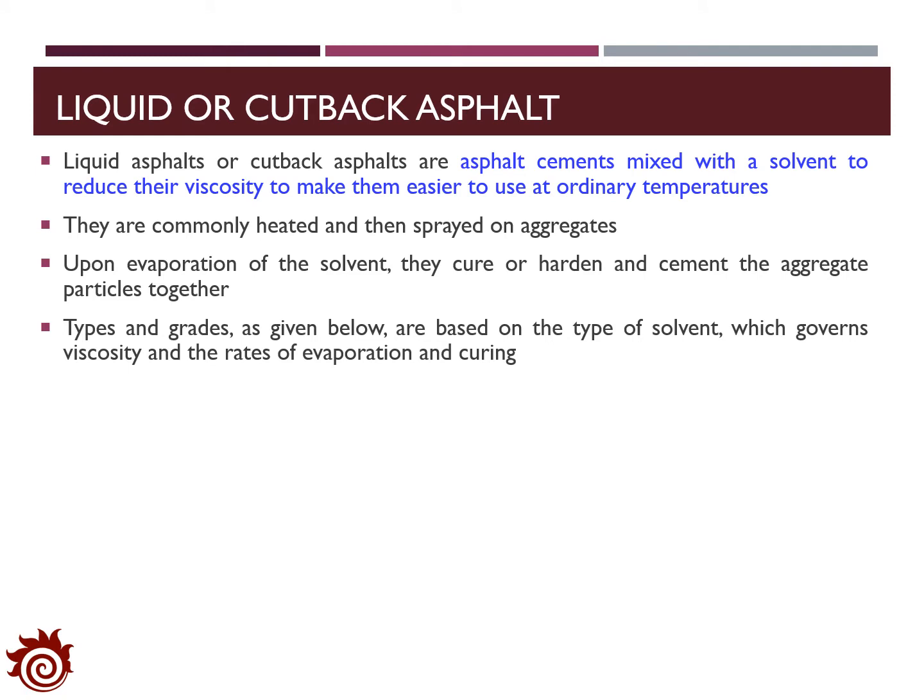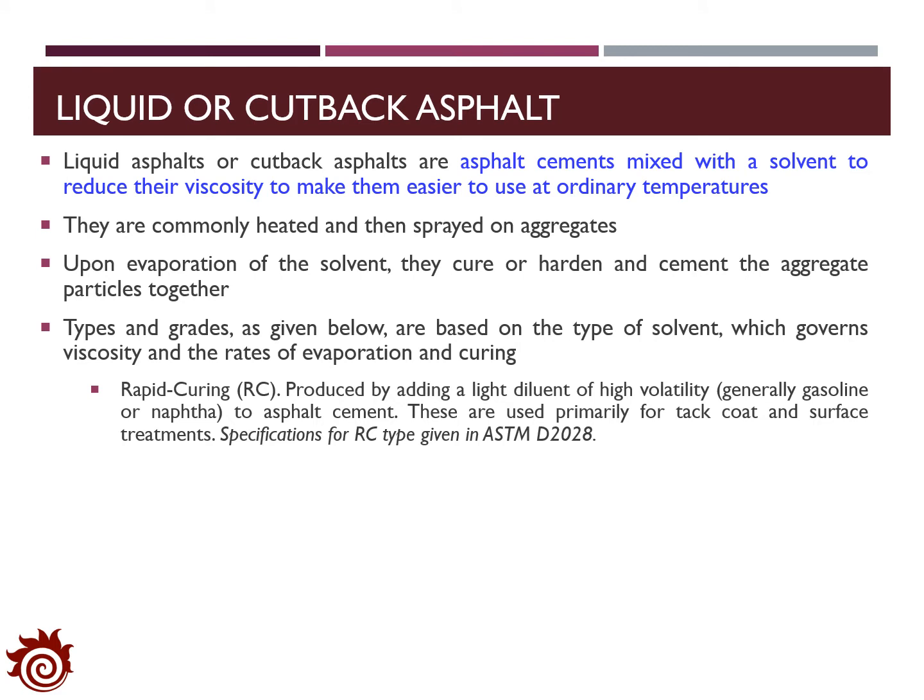In addition, based on the types of the solvent and the rates of evaporation and curing, the asphalt can be categorized into three types. If gasoline is added to the asphalt cement, we will have the rapid curing asphalt. They can be used primarily for tack coat and surface treatment.